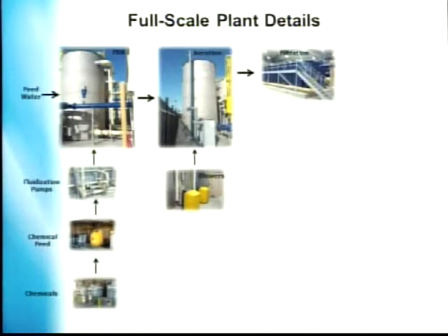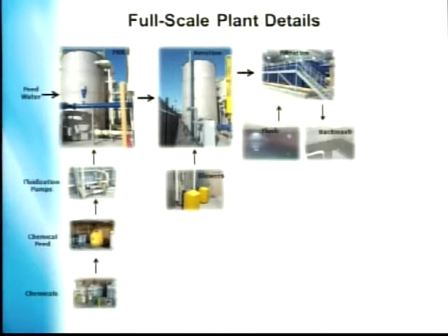You then go through filtration, and these are the Siemens Trident filters. You have a backflush for that system with some backwash water that can go to the DAF, which then you can handle your solids. The idea there, just so you understand, was to be able to recover about 99% of the water by doing this. If we didn't do that, we'd probably recover about 95% or so. So going with the DAF is able to get that last few drops of water back into the feed of the system, and that's what this shows here.